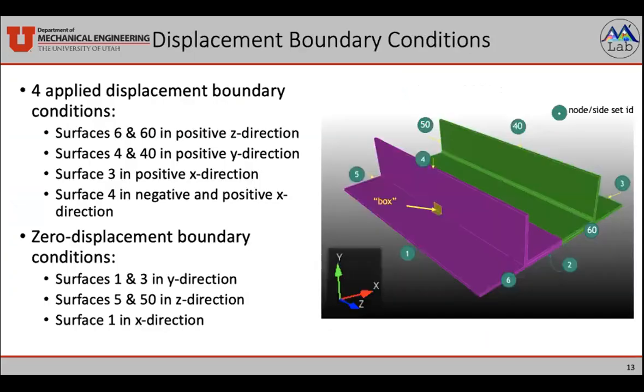So like I mentioned, the line welds had 4 different degrees of freedom, which correspond to the 4 different stress values that you can calculate from them. Locally, on the weld, they would be parallel to these cardinal directions Z, X, and Y, and the 4th one being a moment about this Z axis. And so to isolate those 4 different stresses of the line weld, we applied the following boundary conditions.